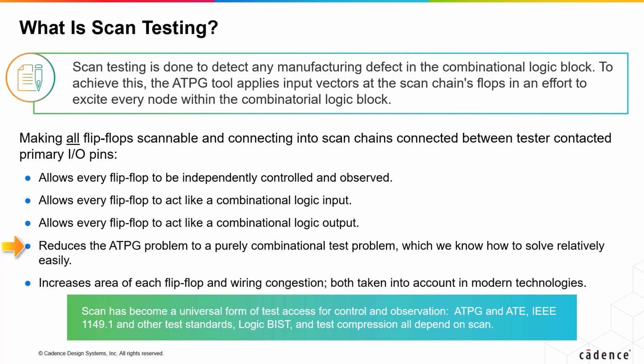Using the flip-flops this way leaves only the combinational logic to be tested, which we know how to do. The cost is a minimal increase in the area of each flip-flop, and some increase in wiring congestion, both of which are taken into account in modern technologies.